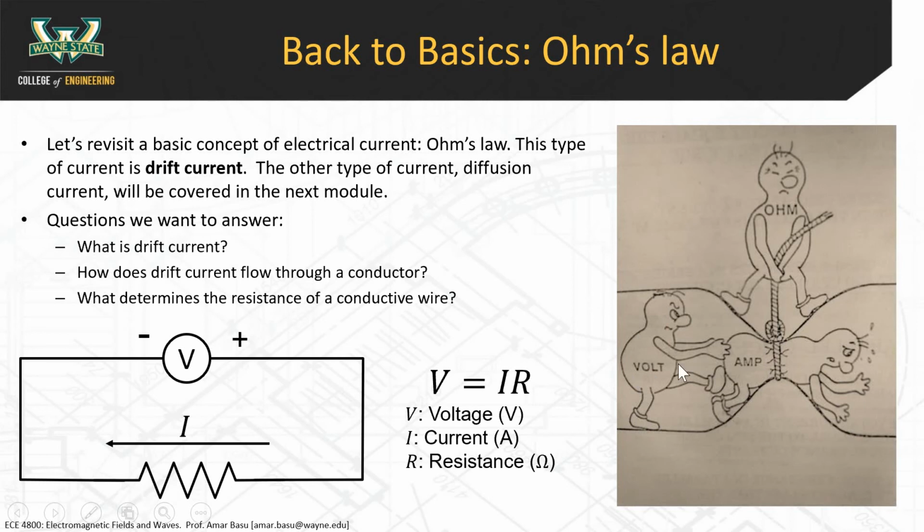The voltage is pushing the charge, which is trying to go through the wire. But if the wire is very, very wide, the charges can move through there very easily. If you have a constriction in the wire, a narrow region of wire, that narrow region has higher resistance. Wherever you have higher resistance, it's harder for those charges to move through the wire because more charges have to squeeze through a small area like this.